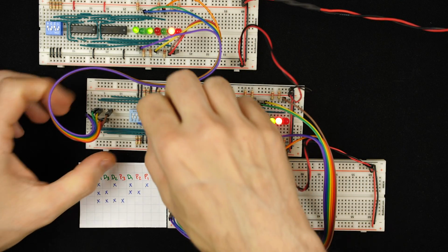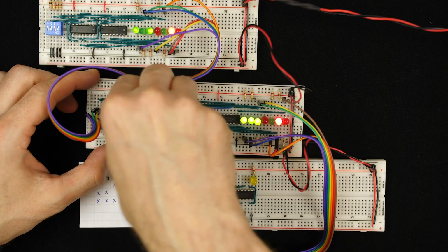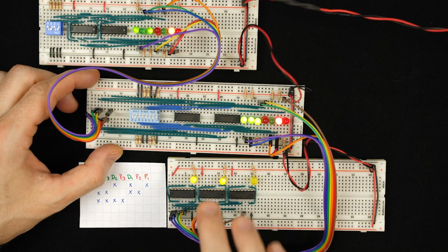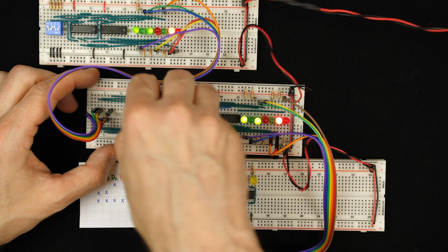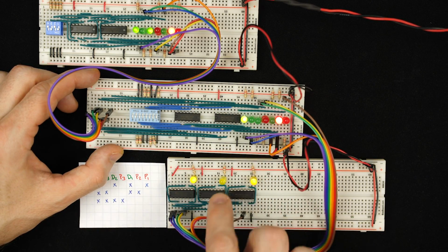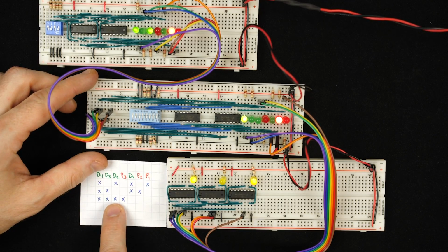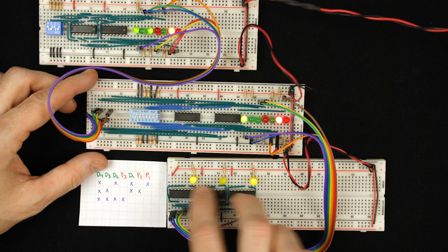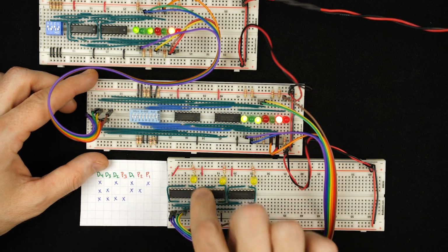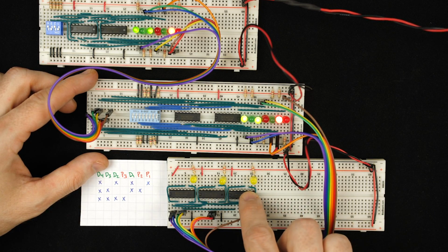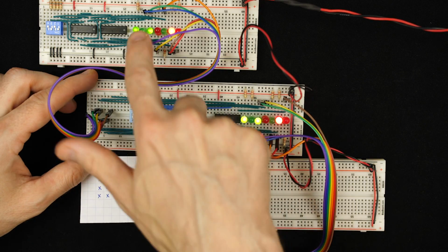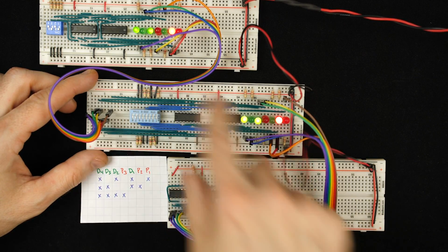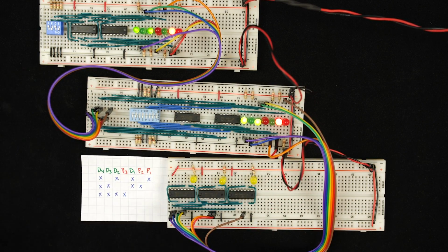So at this point, we're actually able to detect any single bit error. In this case, this is going to be a D3 again, D2. We can detect any single bit error just by looking at which parity bits are wrong. And of course, if they're all off, then that means there's no error, and what we're receiving is correct. That matches what was sent, or what we're reading matches what was stored if we're doing error correcting memory or something like that.